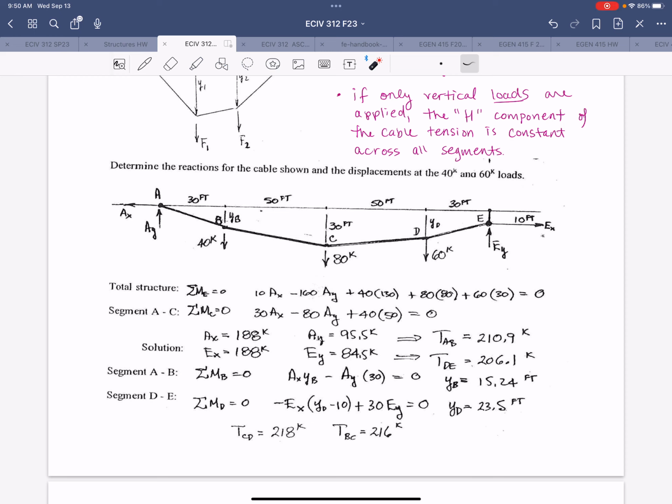So technically we have a distributed load on that top chord, right? But still for our analysis, it's acceptable to use the idea of tributary width to condense those distributed loads to point loads acting at the joints for analysis.